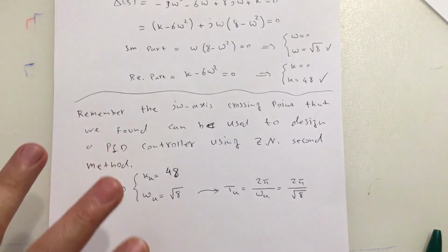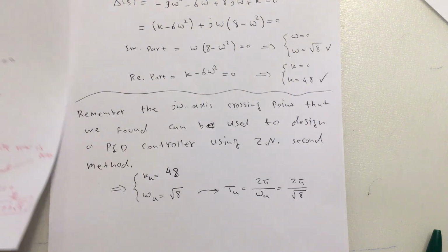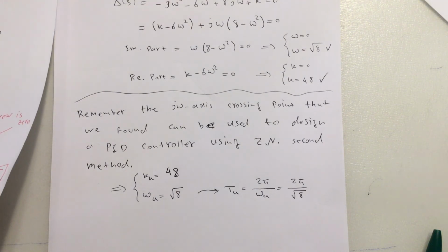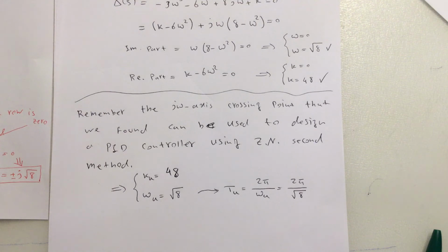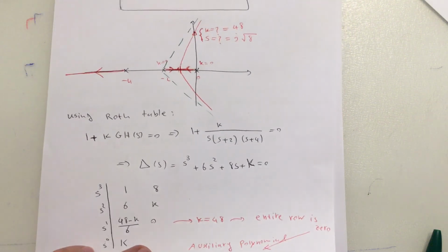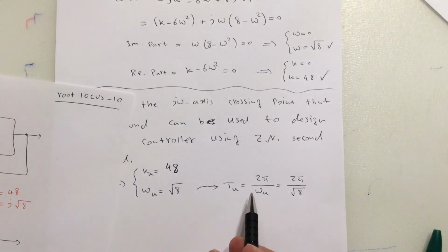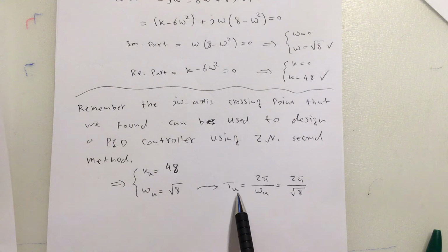I just wanted to tell you here because, in the method I talked about in the last lecture on the PID controller, I said that through simulation you can change the gain such that the step response becomes pure sine. So I'm telling you here that you can also solve the problem and design a PID controller using the Ziegler-Nichols method on paper. It is not only simulation based or experiment based. Theoretically you can find Ku and Tu. How to find Ku and Tu theoretically?